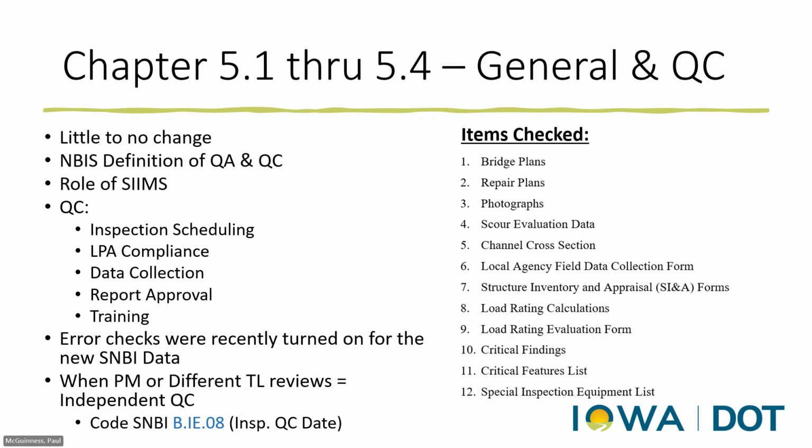So there were very few changes to these sections in the bridge inspection manual. So I just want to talk a little bit about QC and who performs it. Well, quality control starts with the inspectors. Inspectors should review the previous inspection report before they actually go out in the field. It'll prevent surprises. And the bottom line is that preparedness really does lead to quality. Before you leave the bridge site, inspectors should be reviewing all the data that they collected for completeness, making sure they got all the measurements, all the photos. When you do that, you're going to leave the site knowing that you have everything you need to generate a complete and accurate bridge inspection report.